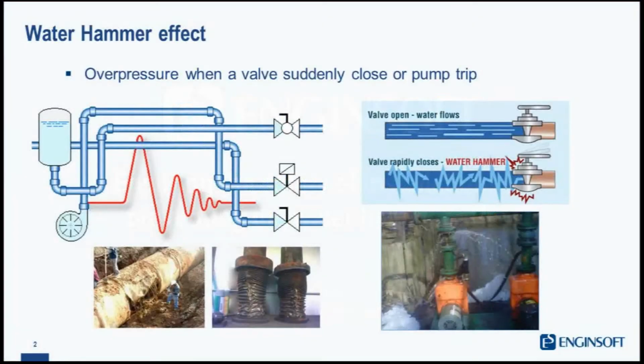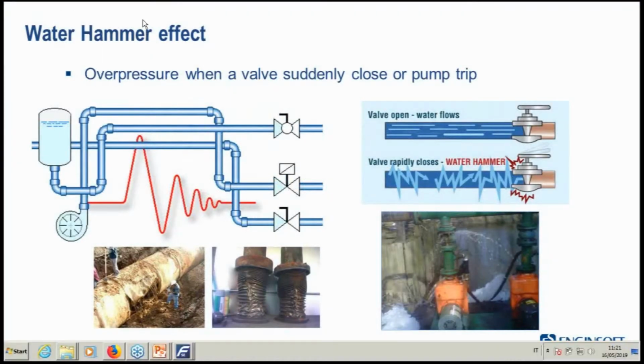Okay, so the water hammer effect comes when you have an overpressure, and this happens when you have a sudden valve closure or a pump trip. So generally speaking, here you have a closure of the valve, and you have to guarantee that your overpressure